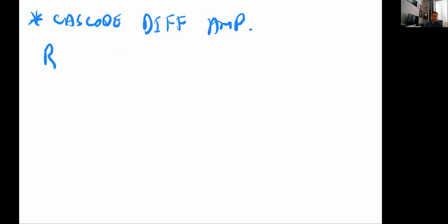So if you go back to figure 9.13 and we look at the output resistance, we see that we have the loads as P channels and the amplification as N channels. So those are the 4 transistors at the bottom of the circuit.